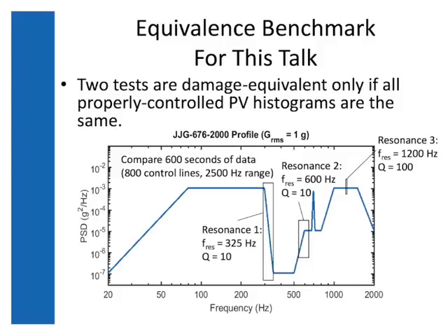That will only have a width of 12 hertz, but because my test has a 3 hertz bandwidth, or bin width, sorry, that is still considered a properly controlled kurtosis. Note also that this profile I have scaled to 1 GRMS, so from now on, any slide that reads acceleration can also be read number of sigmas.